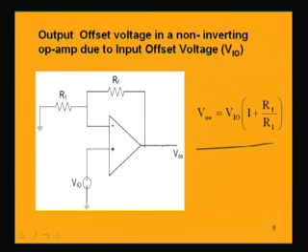source. Exactly this is coming from the input offset voltage, because of which we are getting an output voltage even without a signal. So, we already have a voltage at the output even though both the input signals are at ground, and that is why we have to compensate this output voltage. Whatever output voltage is coming, if we measure it, then we have to compensate it by properly designing a compensating circuit so that this offset voltage can be balanced.